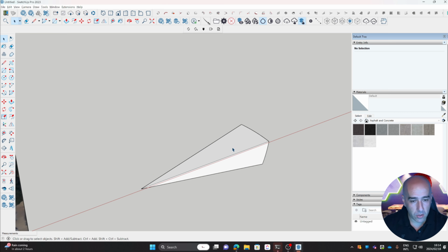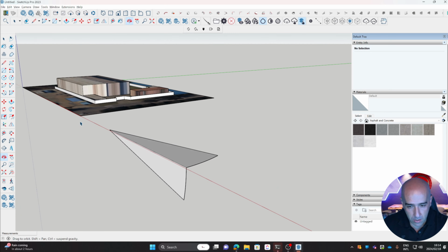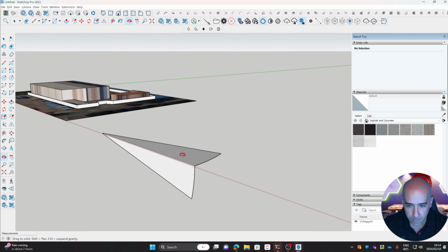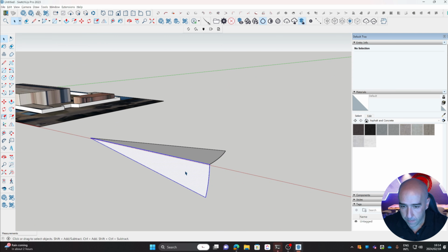Let's go back to the select tool. Now we need to create the other side. Double click in the middle. It will select all the edges. Press the Q button. Okay, and we do want it in this way. Press in the beginning, press again in the end. Press the control key so we can duplicate. Okay, you'll see there's a plus sign there. Now we just move to the other edge, it'll snap, click, and there, we've done the other side.